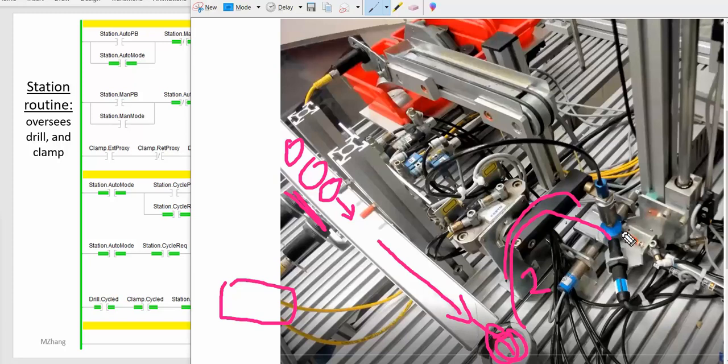And then same thing again, when station 3 processes the part, right? So there's part present, raise up and shoot out, and then automatically that part disappears, right, in front of the sensor. So all this is not controlled by the operator manually anymore. It's because the stations work together in the sequence, right? So that part, we need a resync, right?